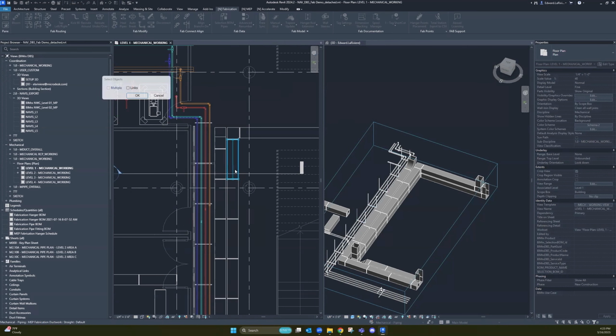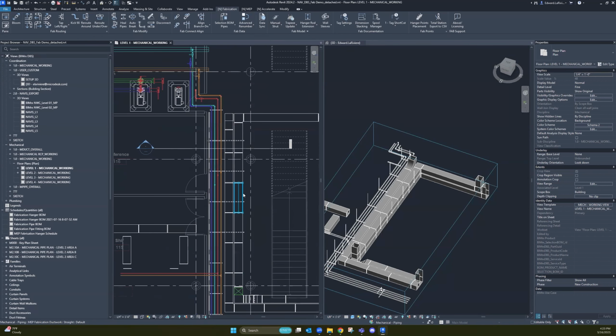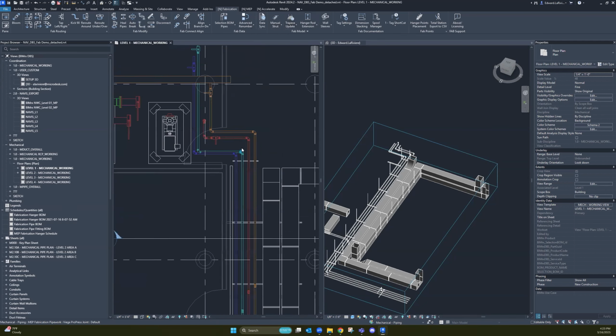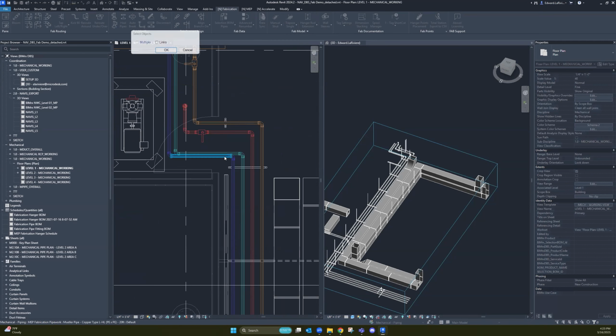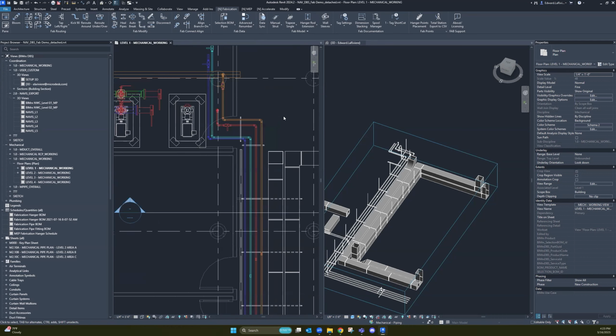Trapeze Update is that tool that allows us to go ahead and grab a few elements, click Finish, and then extend those to go further than the original layout. So a quick way to go ahead and update where those elements are located and update the height that they're associated to as well. Outside of that trapeze update, there's also a trapeze single for when maybe I don't want to run the entire array here, but I know that I need a trapeze hanger to run across all 4 of these. You'll click once to place the first one, again to choose that extension, and it will automatically extend it between both of those.